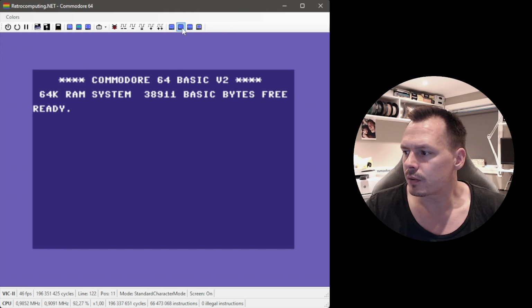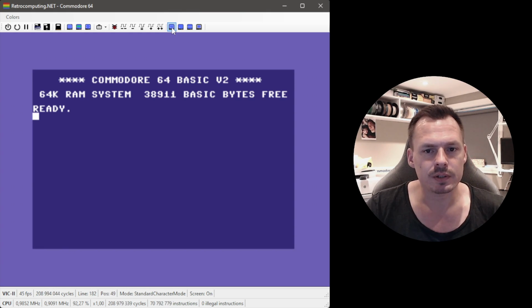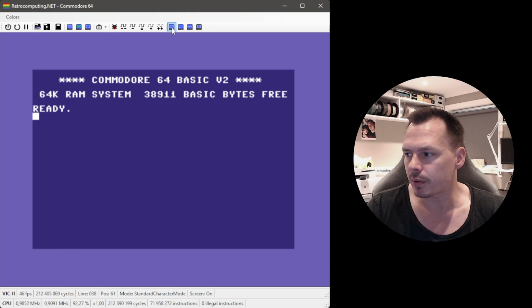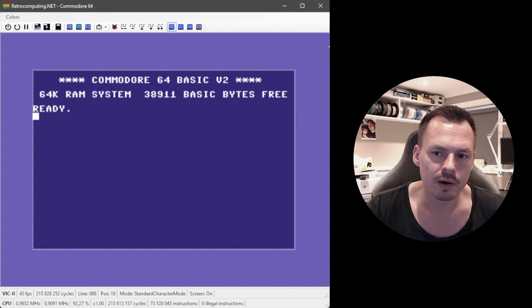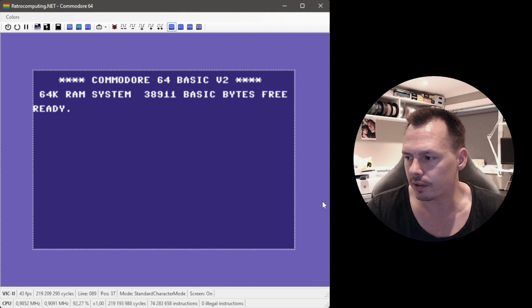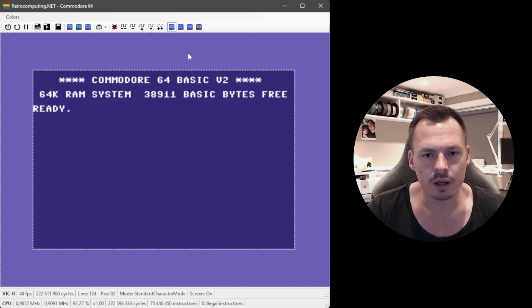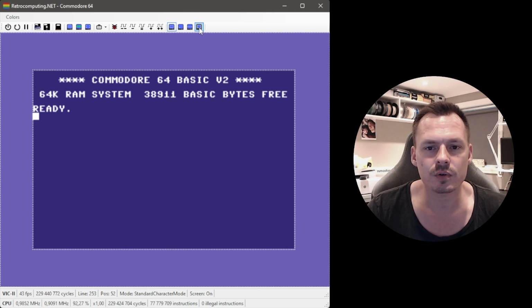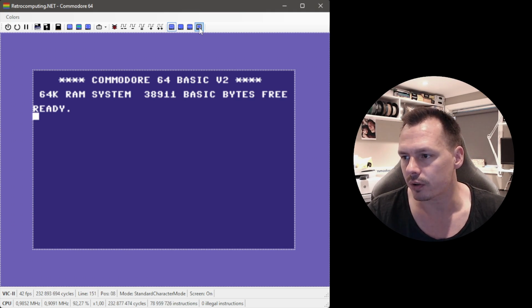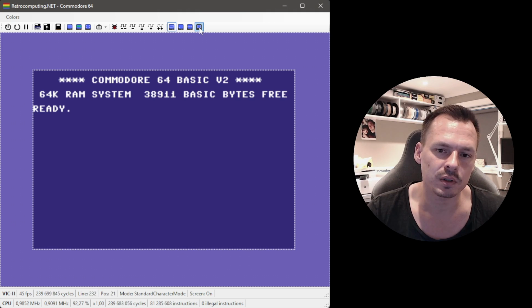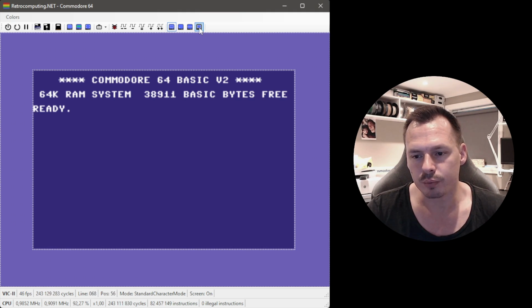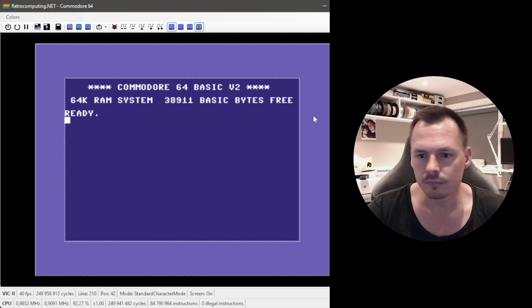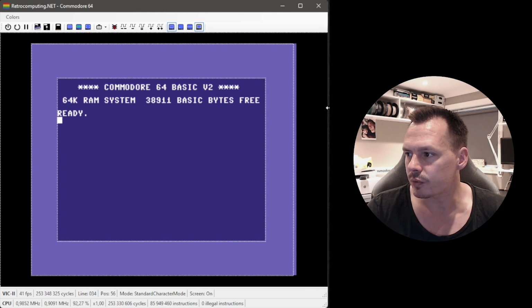So these last 4 buttons, those are debugging tools for the VIC II. First one is for showing the extents of the different parts of the screen. So we can see that we have outlines on the main screen area and the border area. And if I were to click on this icon, it's going to show the whole part of the screen, because if you know how these old video signals work, you actually have parts that are not shown on a CRT screen, but it's still part of the signal, and it needs to be emulated to do proper screen emulation. So when I enable this, it's going to screw up the capture a little bit, but let's just try. Yeah, we overflow a bit, but let's just squeeze it.